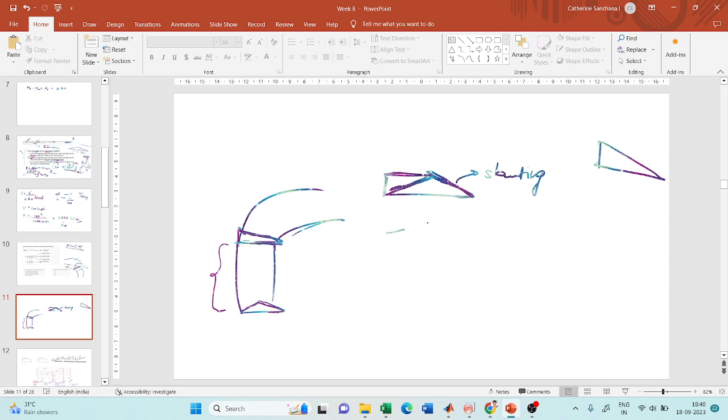So this triangle you will convert to something like this. Earlier it was at this dotted line. Now this dotted line you are bringing to a flat section. This is known as tangent runout.